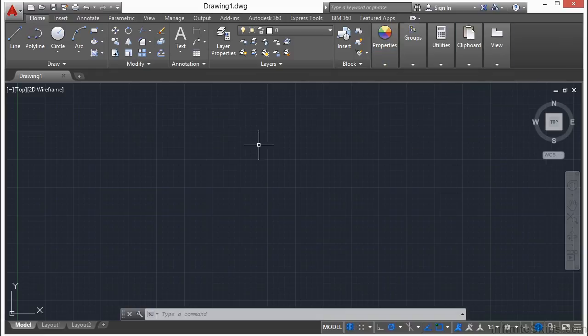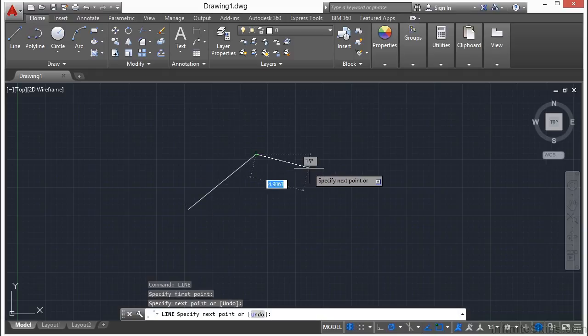Now, another way to execute commands in AutoCAD is through what's called the command line. It's found here at the bottom of the screen. That's this guy right here. You can directly input commands right into it by typing them on the command line. So you can click inside here and then start typing in a command like the Line command. Press Enter, and now I can draw lines.